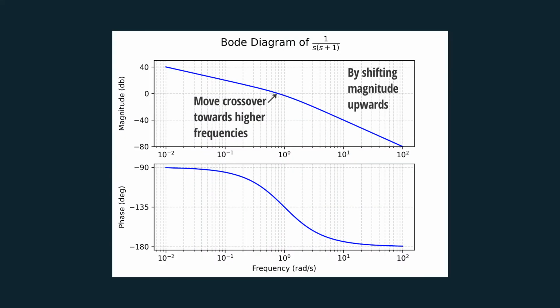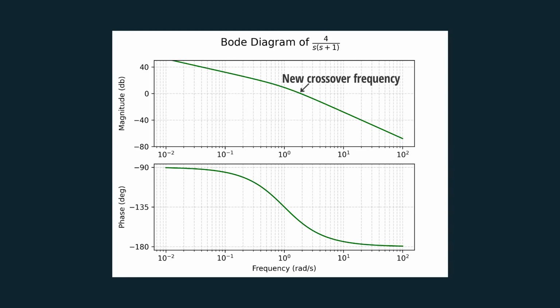The second step is to choose a gain value to satisfy the bandwidth requirement. A good rule of thumb is to set it so that the crossover frequency is half of the desired bandwidth. After some iterations, I went below that by setting the gain for around a third of the desired bandwidth instead of a half.